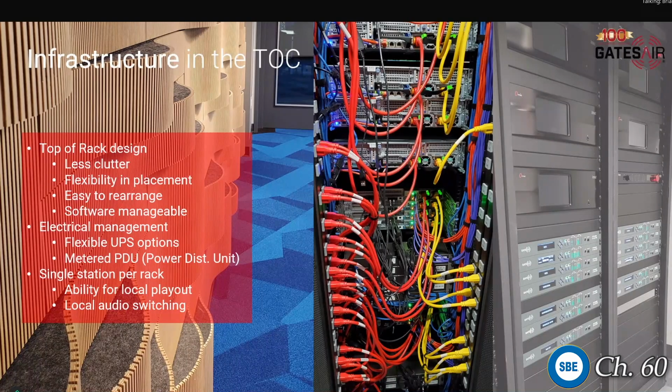You can see in this picture that this particular facility, they have the cables on the left, the plug mold strips are most likely on a UPS, and you can see that they use red on the left and yellow on the right, and you can see that those servers actually get a feed from both of those panels, so they could have totally separate UPSs.